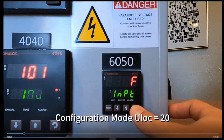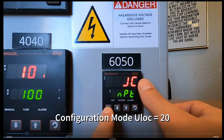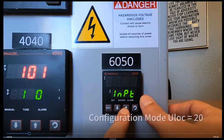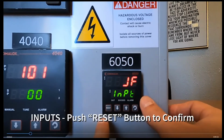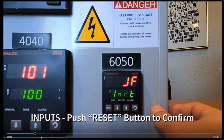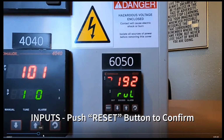For the 6050, it's the same thing, but it's that reset button. Just as a reminder there. So the configuration mode will be pretty similar to the 40 series. Similar input type, J-type thermocouple, Fahrenheit. Always hit that reset button.